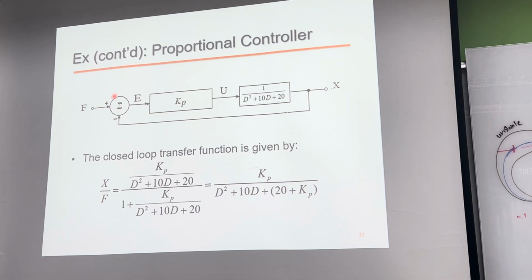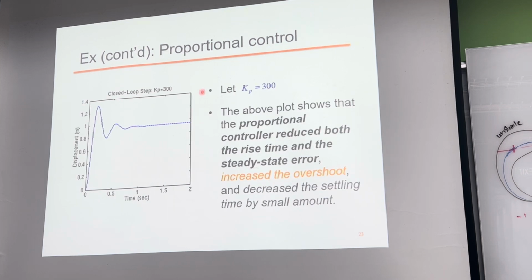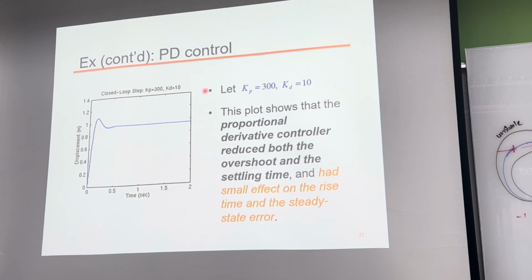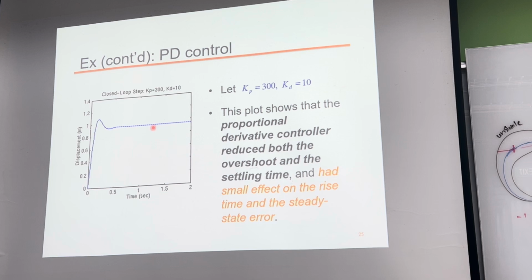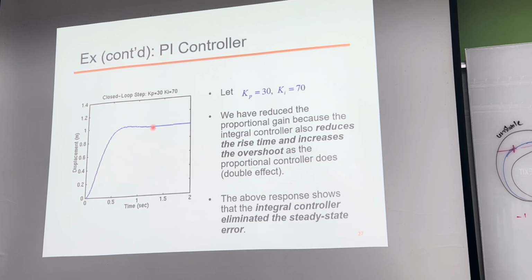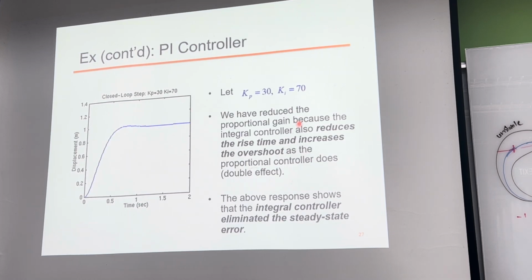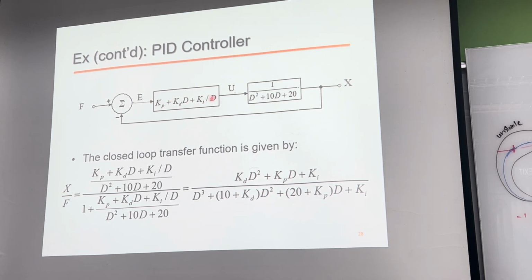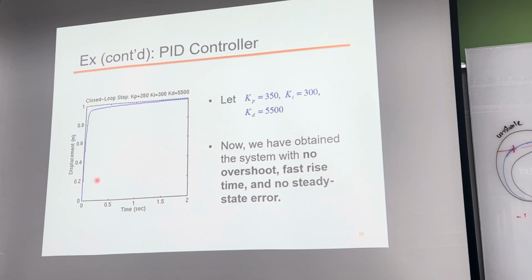In our block diagram, one new block will be added so that we can get different curvature. Here they put Kp as 300 and Kd as 10, that's why we get this curve. Then again they have a Ki. When they put all the constants Kp, Kd, and Ki together, it gets stabilized. The numbers can be iterated manually, or they can be auto-tuned with software.